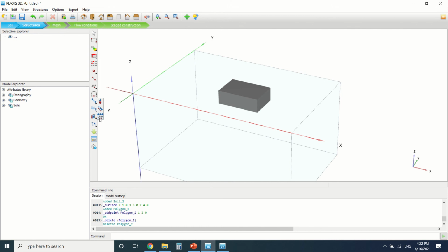The load, for sure there's a surface load, not like the 2D software. Here there's displacement. Here we can create structure. Interface, there's a negative, a positive. The negative and positive interface do not mean anything. An interface is an interface. It's just to annotate them. Here it's a geogrid. We can create a geogrid with it. This is the plate, embedded beam. As you can see here, we create surface and here a plate. These are for the structure.